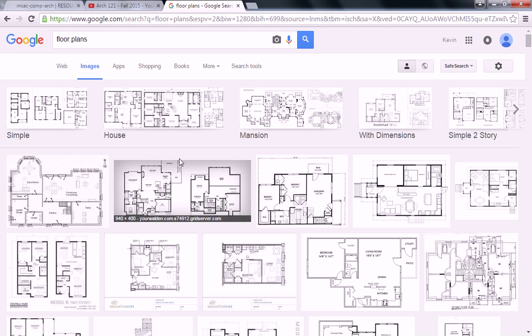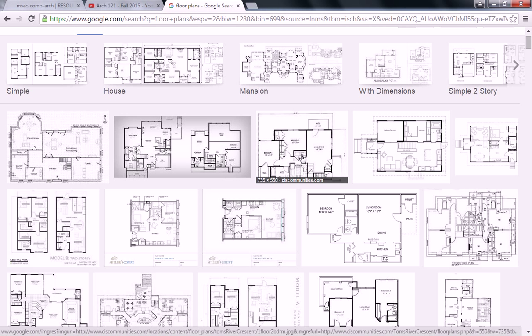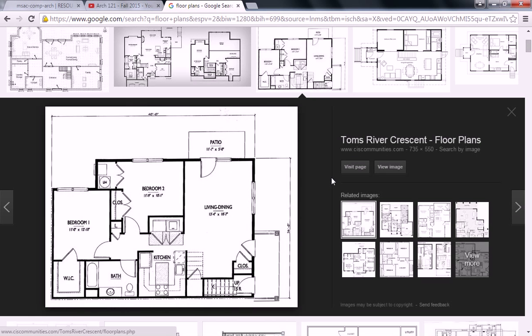Yes, it's a section. So let's talk real quick about different architectural views, I guess, and we'll get into this in more detail. But I want you to know why we're developing an interior floor and stairs. A floor plan is essentially a horizontal cut through the building. It's as if you took a hot knife and just sliced the top off of a building at a height of usually about 4 feet high.